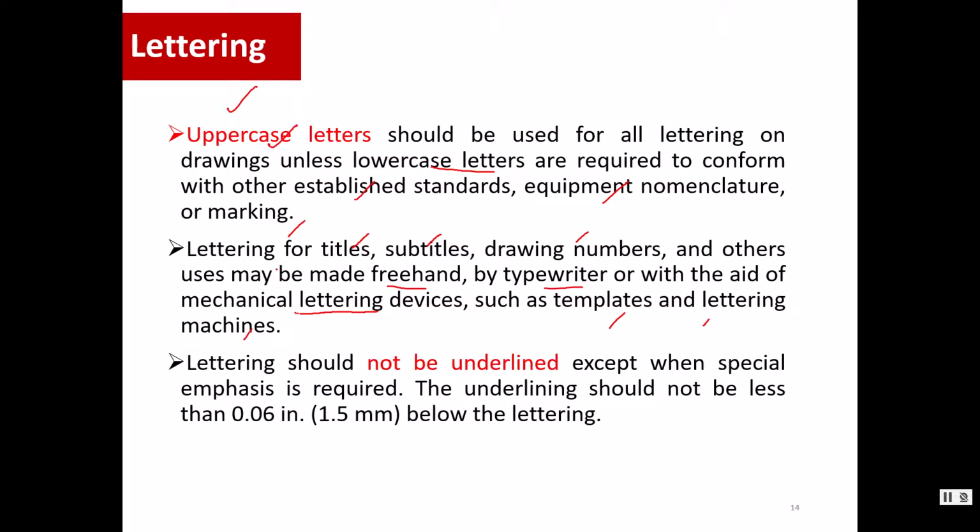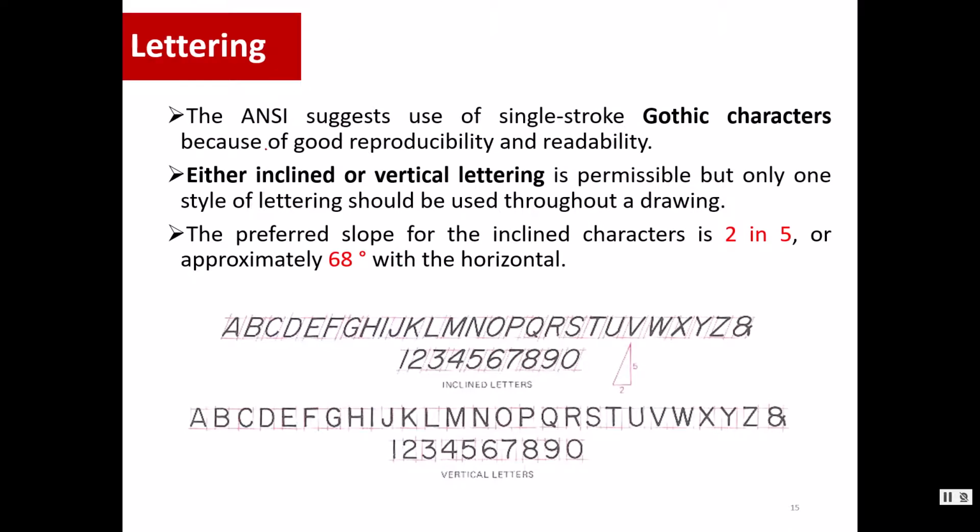You can do the lettering freehand or using a typewriter. The lettering shouldn't be underlined except when special emphasis is required. So these are some of the standards for lettering for manual drawing. ANSI, the American National Standards Institute, suggests using the single stroke Gothic character.